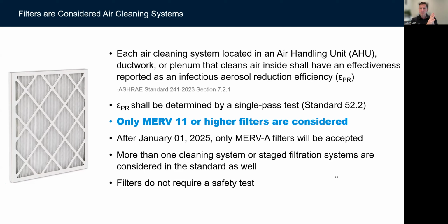That static charge loses its effectiveness over time, but an initial brand new product tested in an ASHRAE 52.2 test will have a better removal value on day 1 than it will on day 30 or 40, after it gets a little bit of loading on it, moisture, other things that drop off that static charge, okay? So with MERV 11A, you actually discharge the filter through a salt spray or whatever evaluation, clean it off, load it, and then run it.